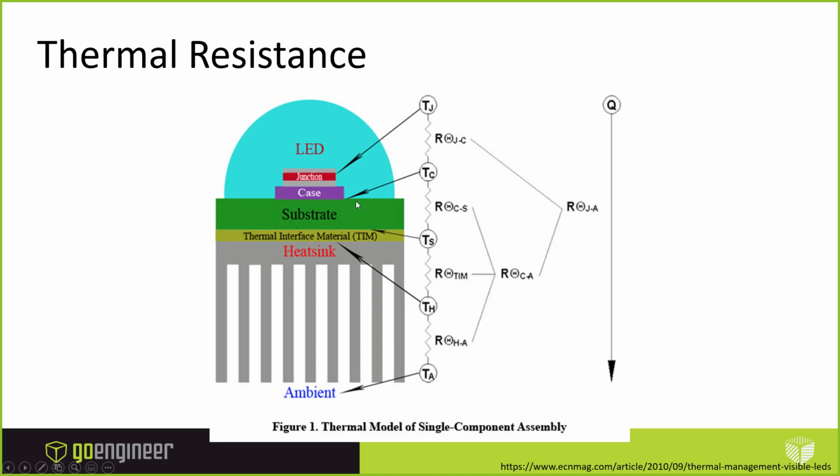But then some of these we'll need to model ourselves, either by running thermal studies or flow studies. We'll need to come up with the substrate material's thermal resistance. This one might be provided by the manufacturer. And then the heat sink to the ambient thermal resistance, that's done by a flow study. We can figure out this thermal resistance by running a fluid dynamics study, running air over this heat sink. So we can kind of fill in the blanks.